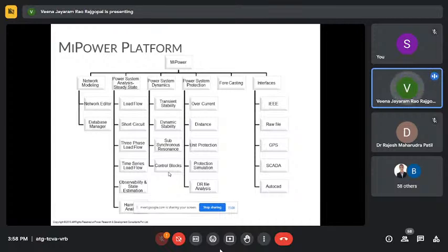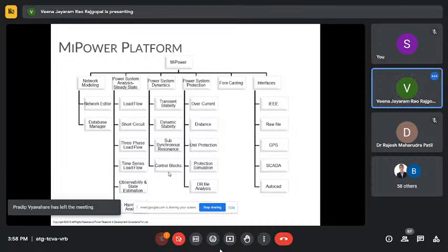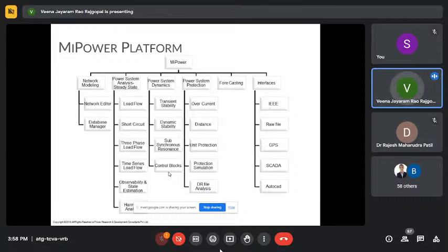During such situations, industries do this harmonic analysis, placing the harmonic sources wherever they are, and comparing the measured value with the analyzed value of the total harmonic distortion. That is part of the harmonic studies. Also, when harmonics are introduced, how do you reduce them? You have your filter design, and when you put that into the system, you can analyze how it is going to reduce your distortions.